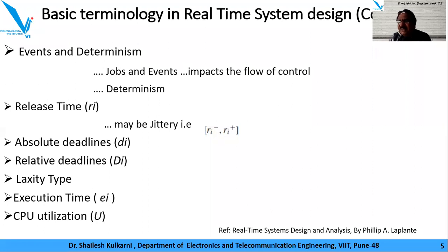But as we know, as the complexity of the system increases, by virtue of an increase in the input variables, the size goes very high when we go with FSM techniques. Though the FSM technique is a very foolproof approach for determinism, it cannot be used for applications which have a large number of inputs. That is the reason we really don't follow FSM techniques for real-time system design.